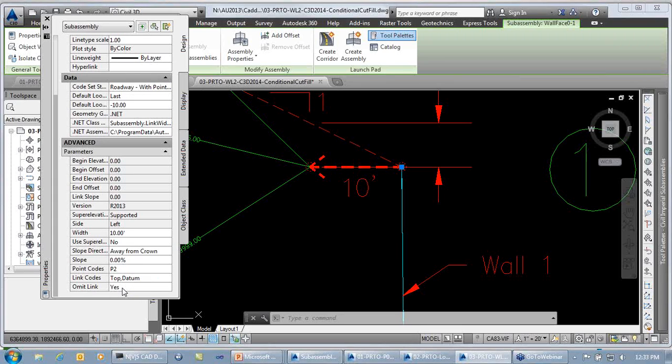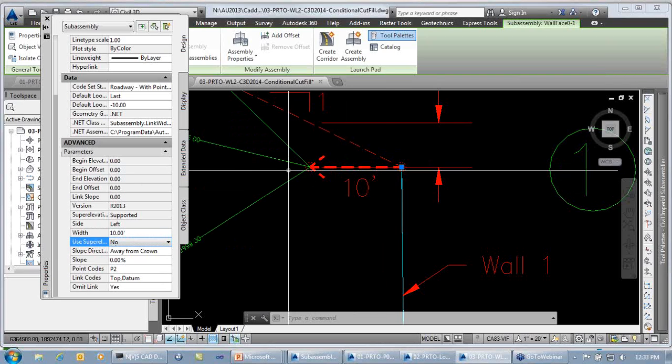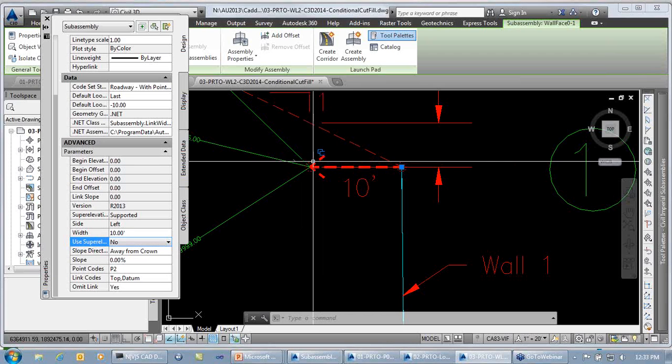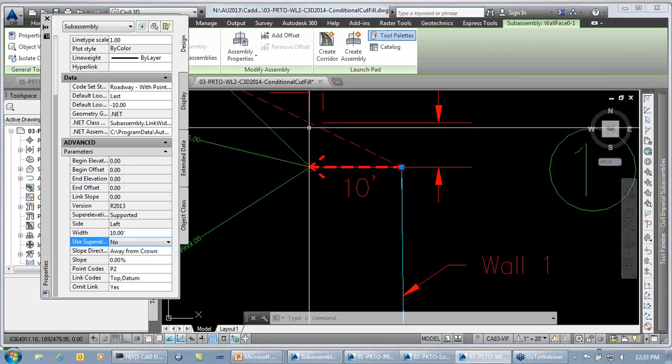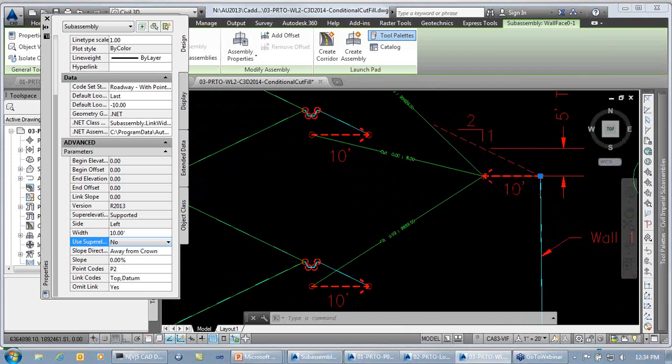And instead of just moving the assemblies, by doing it this way, I can come in here and say, well, if I want 20 foot, it's real easy. I can click it. That's now a 20-foot offset. If I want it back to 5 foot, I can click it and bring it back to 5. So it just allows me to quickly edit and control where these conditions are going to be located. So we're now 10 feet over, so I know at my 2-to-1 slope here I need to be 5 foot deep here. So I've got 3 conditions.